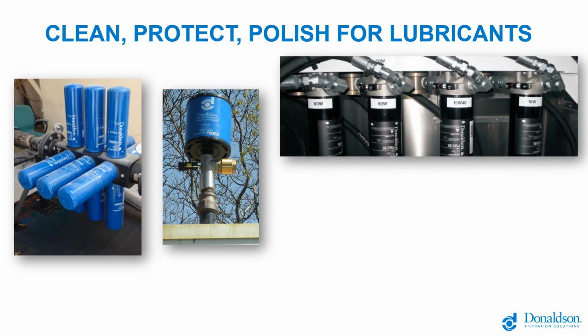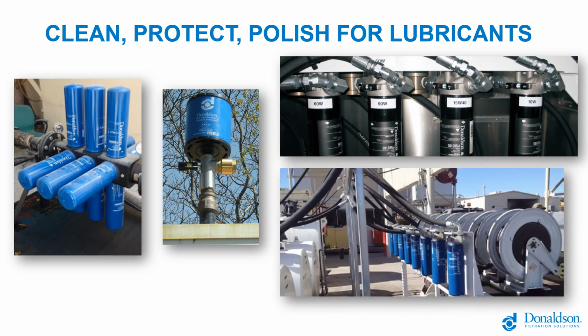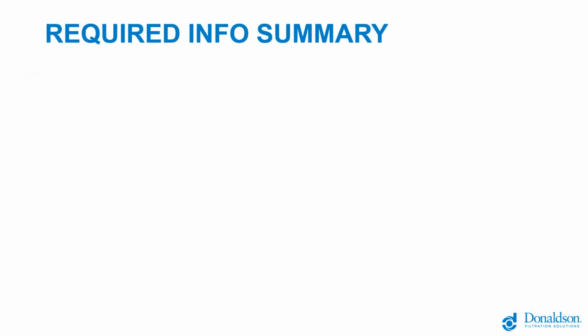And then you're filtering with high pressure bulk HP on the high pressure hose reels, or possibly low pressure one-to-one air operated diaphragm dispenser systems with the higher capacity, lower pressure drop filters that can handle the higher flow right there on those low pressure hose reels. So for every particular site, but just to give you an idea.